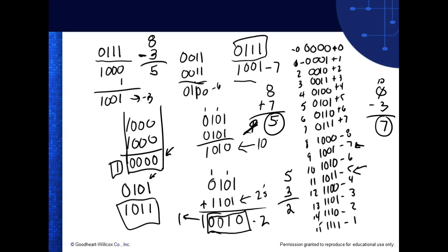There goes the addition. So what 2's complement gives us is the ability to represent positive and negative numbers. But what it really gives us is the ability to subtract by addition. So when my microprocessor is told to subtract a number, it treats everything like signed numbers. It changes the sign of the subtrahend and adds, right?